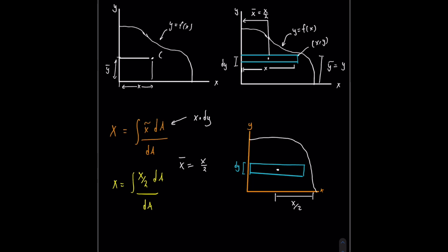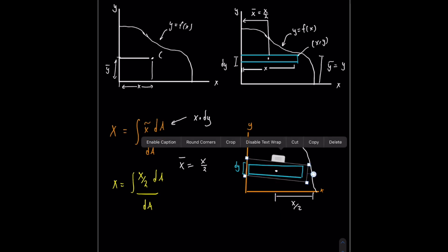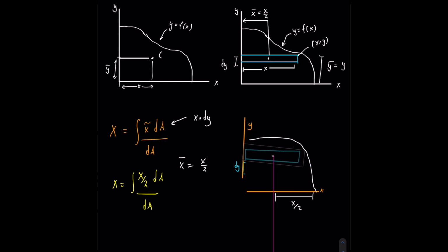Now, as before stated, you're going to have your y constant as you move it up or down, and your x will still remain in the same location, x divided by 2, half the distance of x. This here will give you your centroid in the x direction, or your distance here, as stated here. X centroid equals x divided by 2, and that you plug into the function.